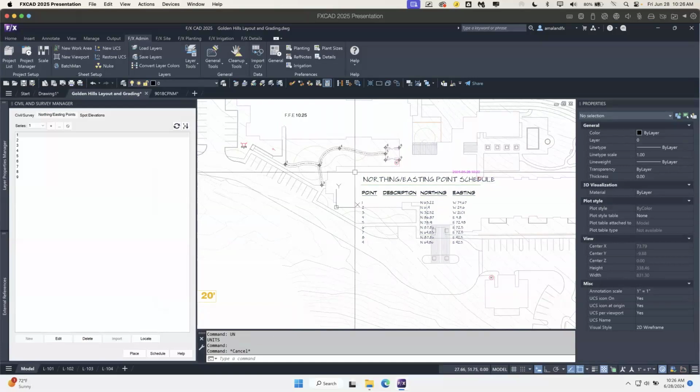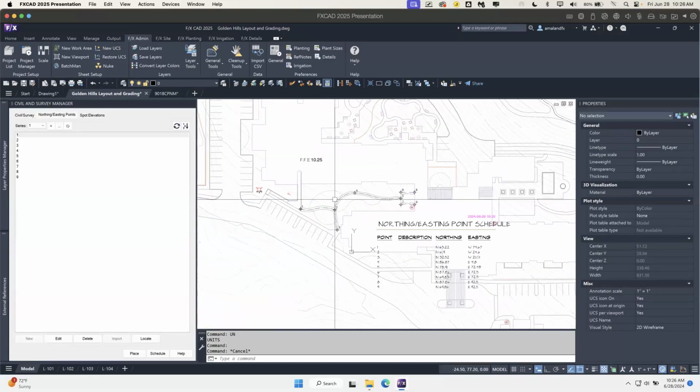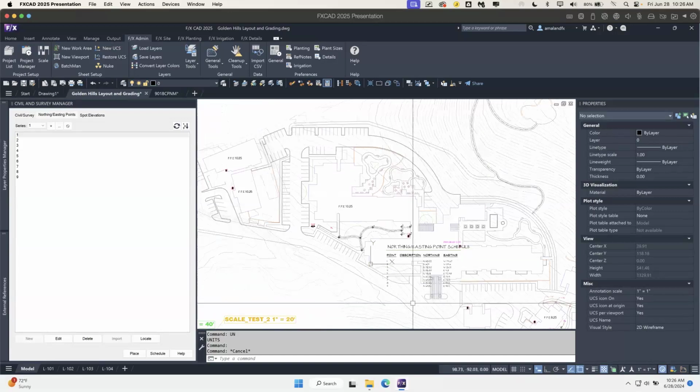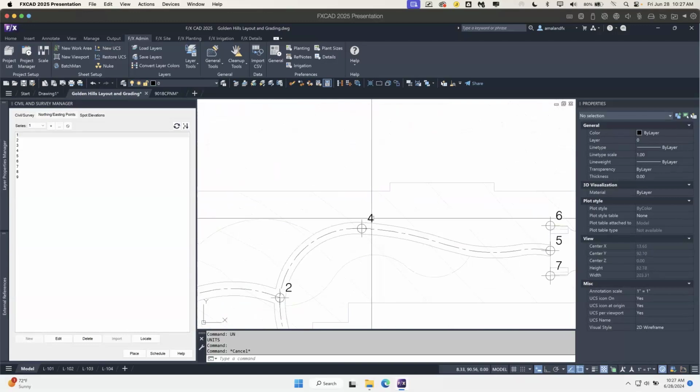So then, of course, the next thing was the thing that we had foreshadowed, which is the new series tool. It starts out numbering 1, 2, 3, 4, 5, 6, 7, 8, 9. And we can actually add series in here. So you might use series for things like marking out certain areas and separating them out in the schedule, and being able to go back over to different areas and continue marking them out without having to go into each one of these and renumber them.